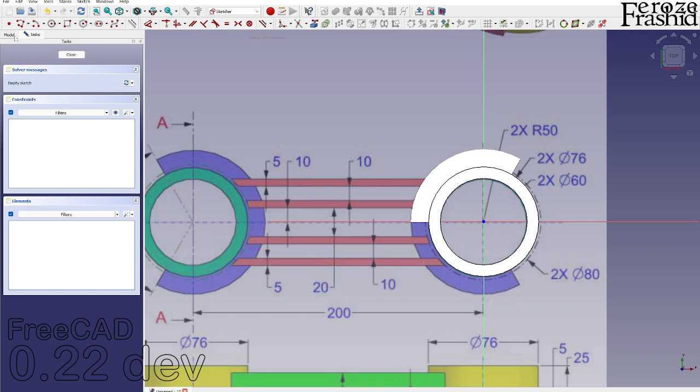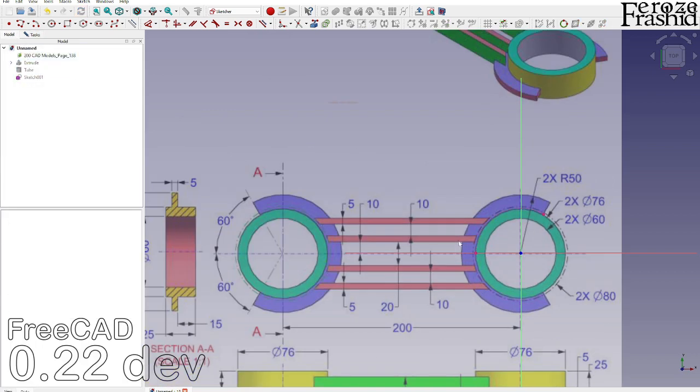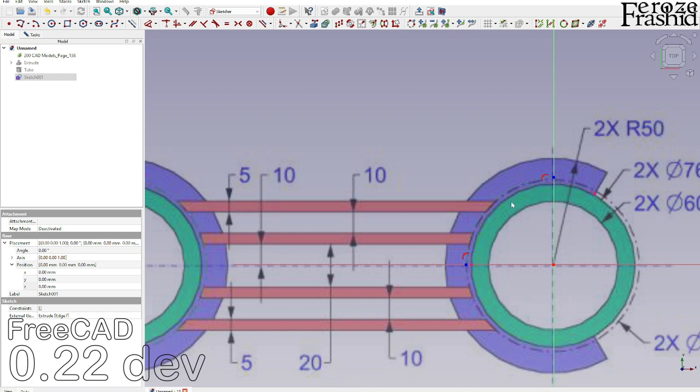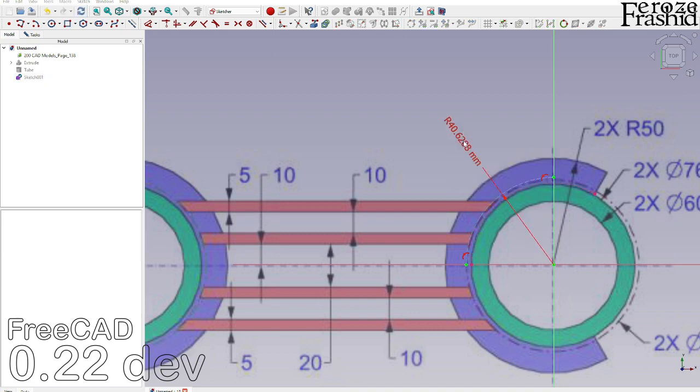I'm going to go ahead and hide the tube. So we'll have to draw construction geometry, an arc here, to get a reference. Let's switch to construction geometry, and that's the shortcut G N. Then take the arc, bring it up here, and maybe take it up there. This one is very tough to see, but that is diameter 80.